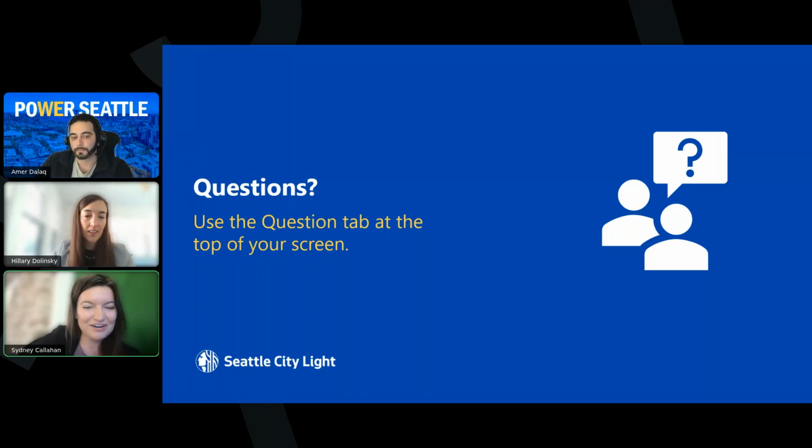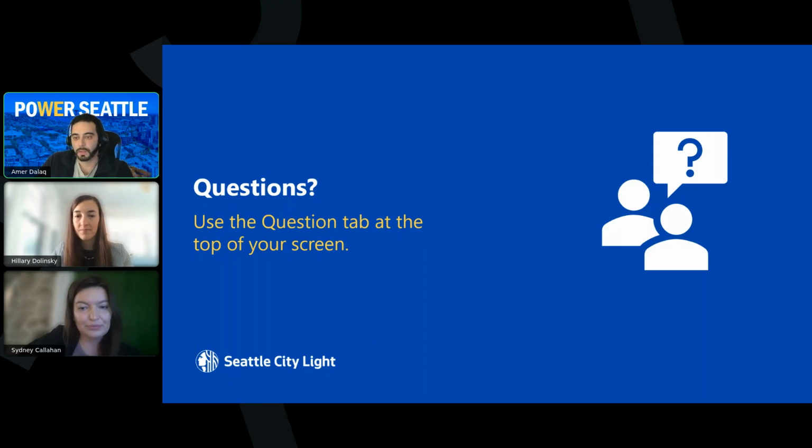Okay, I think I'm back up and running. Amer, this might be another one as well. So it's, why is Seattle City Light maintaining a no export position with respect to DERs connected to network grids? Yeah, so the way our City Light's network grid is designed, there are several protection devices like network protectors in place because it's all intertwined and interconnected together. So that would typically usually trip those. So one way to protect that is to not allow DERs to export.